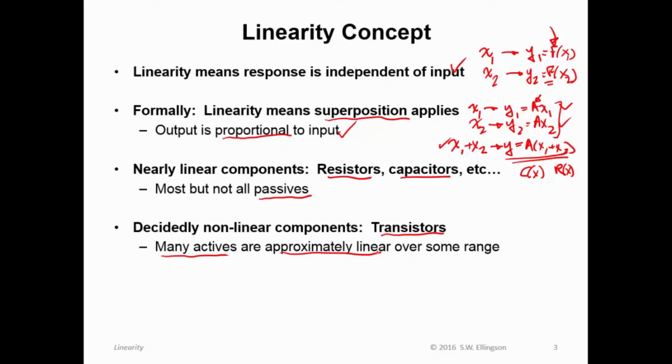However, just to underscore the fact that they are fundamentally nonlinear, just recall, for example, for bipolar technology, that the collector current is dependent on the base emitter voltage through this relationship, which is fundamentally exponential. That is not linear. It only seems linear because we constrain the range over which the input, VBE, can vary, and over that range, IC varies in an approximately linear way. In other words, the exponential behavior here is not apparent. It seems approximately linear. But of course, as VBE gets large enough,